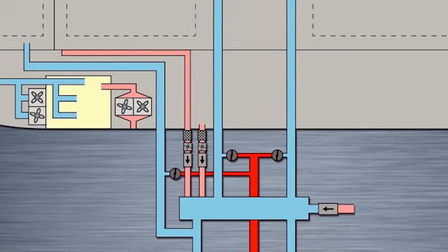Auto recirculation operation has 2 modes, ground and in-flight. On the ground, the right recirculation fan operates constantly, and if both air conditioning pack switches are high, the left recirculation fan operates too. During flight, the left and right recirculation fans operate while both air conditioning packs are operative. Air from both fans passes through a recirculation fan check valve that prevents any form of leakage or loss of conditioned air back into the mixed manifold from the recirculation system.